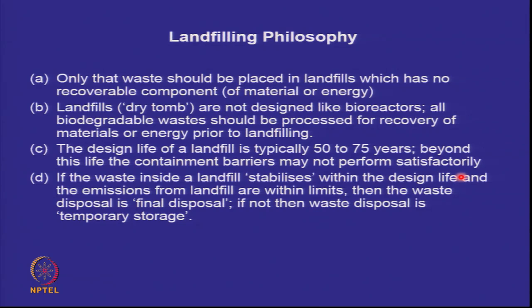So just to recall the landfilling philosophy, which we had done last time, only that waste should be placed which has no recoverable component. Landfills will be designed like dry tombs, no water in, no water out, and not like bioreactors.